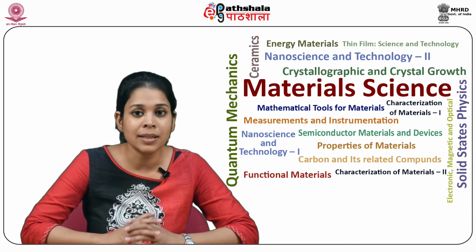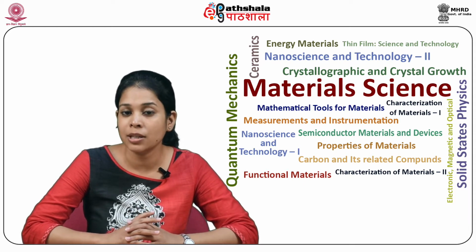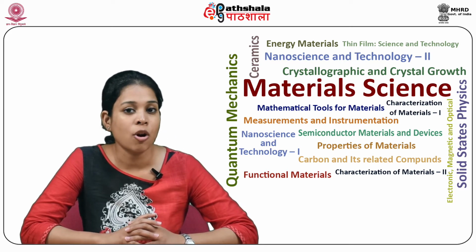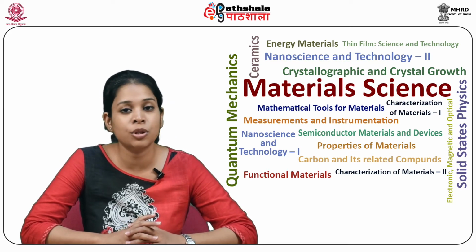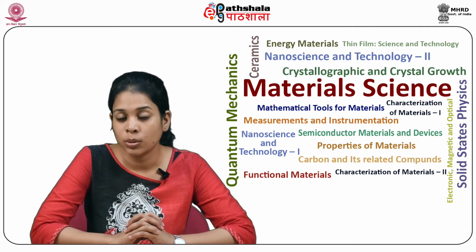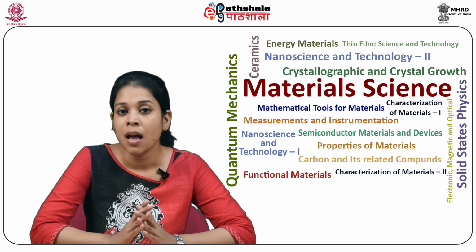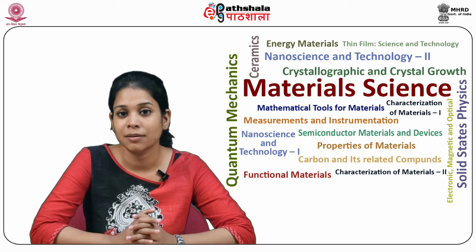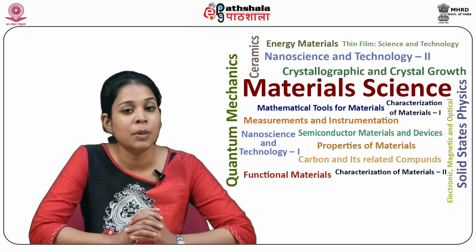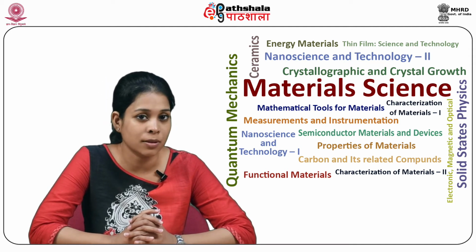The ferrite compounds have extremely low cost, being made of iron oxide, that is rusted iron, and also have excellent corrosion resistance. They are very stable, difficult to demagnetize, and can be made with both high and low coercive forces.